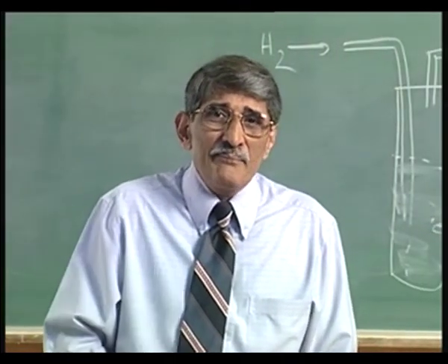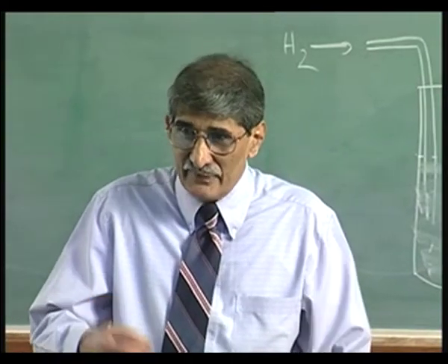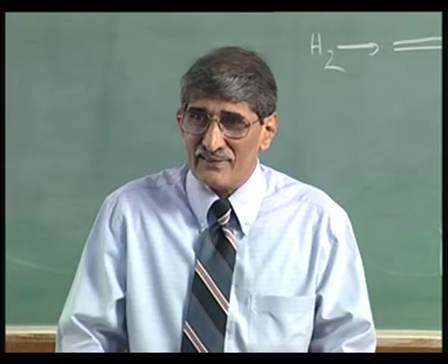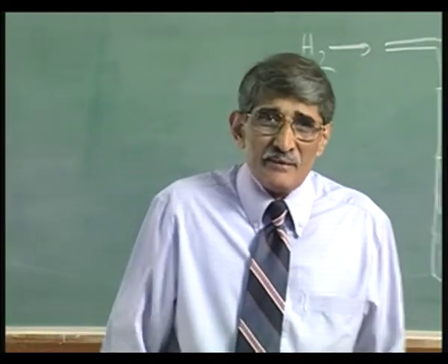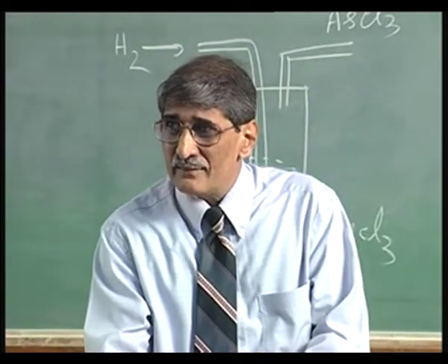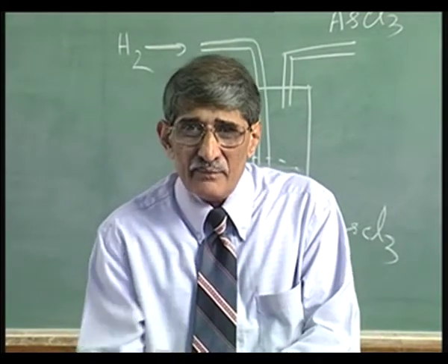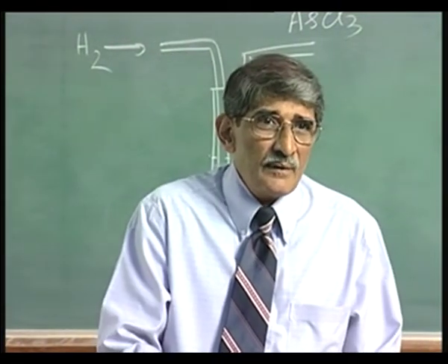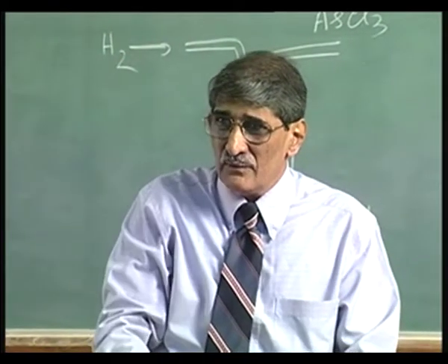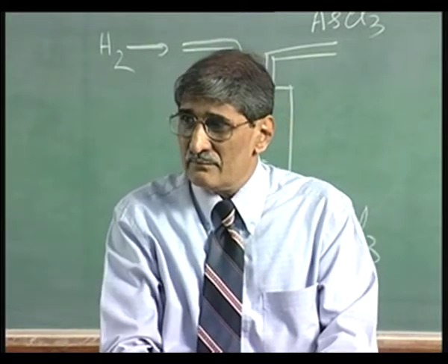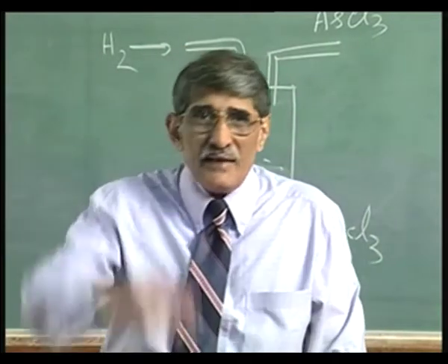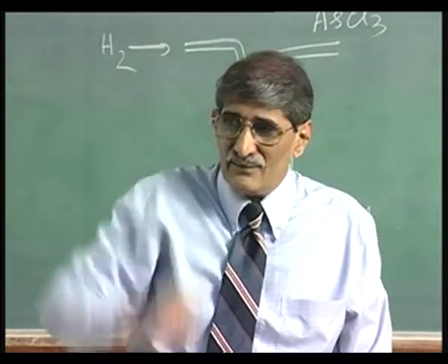A very good example of physical transport, I am sure all of you are familiar, is vacuum deposition. What do you have in a vacuum deposition system? You have a chamber in which vacuum is created, you have a filament which can be heated, and you keep, for example, if you want to evaporate aluminum, that is you want to transport aluminum onto silicon or gallium arsenide, what you do? That filament is heated, you put aluminum there, heat it, it melts and evaporates, and it goes all over and onto the substrate. Okay.